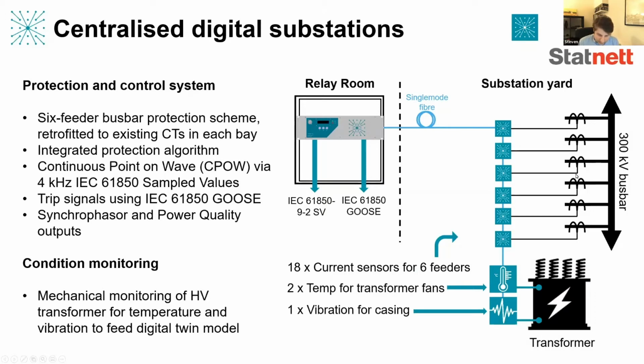So we've seen a lot of drive in the industry lately towards a centralized approach to protection and monitoring systems in substations. For example, it's a regular feature at the PAC World events. So essentially what this means is consolidating multiple functions which would normally be served by dedicated relays, each with their own CTs and VTs connected, into a single device which performs multiple functions, going well beyond the multiple functions that typical modern relays already provide.